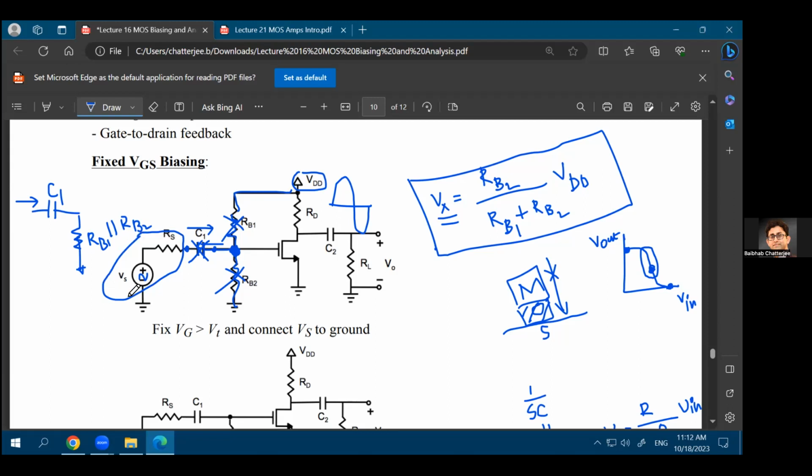You'll just assume that this voltage source is good enough that it can provide the correct AC as well as the correct DC. So for example, let's say you needed a 5-volt DC here, but the DC of this voltage source was 0 volt, it had a 10 millivolt AC swing. So DC was 0 volt, but you had a 10 millivolt AC swing. If you need a 5-volt DC voltage at this point, you have to create this DC biasing network, and you have to couple the AC signal using the capacitor.